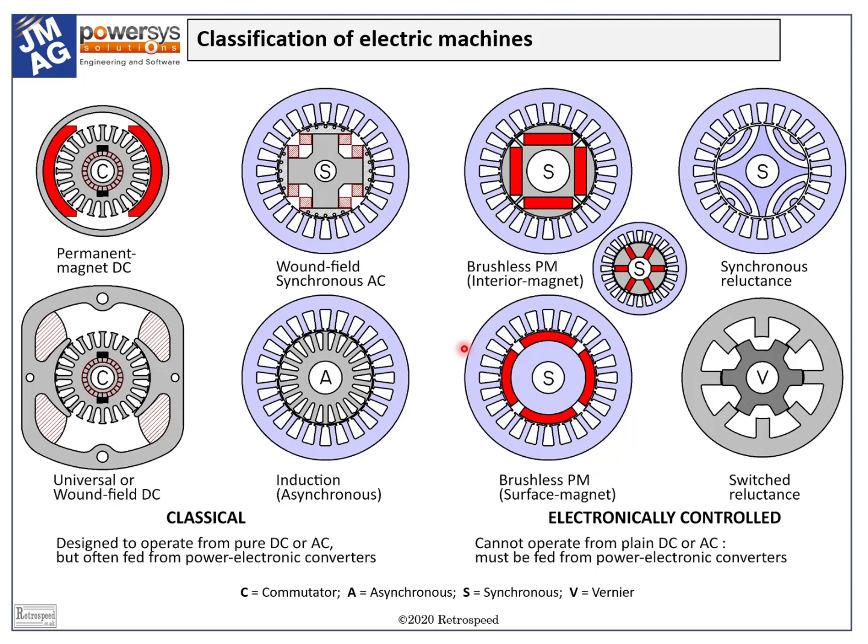But they don't. The equations of all the AC machines are more complicated because at first sight nothing is constant. The flux rotates while the currents and voltages follow more or less sinusoidal waveforms in time. Also, in the AC machines, we have to control 3 currents instead of 1, and in the case of the wound field synchronous motor, the field current as well.